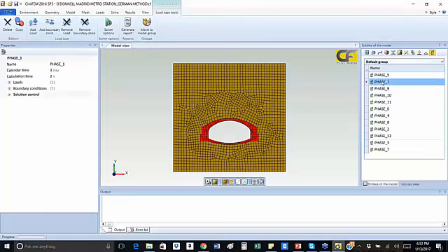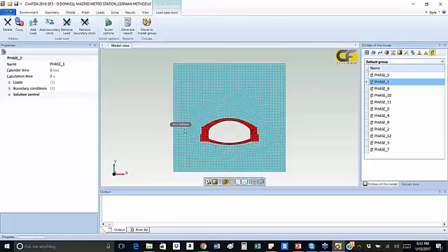We have defined different types of load as phases. Each one of the phases is a construction stage and contains the calendar time of construction. Again, this is the time at which the load will be applied in calendar time.